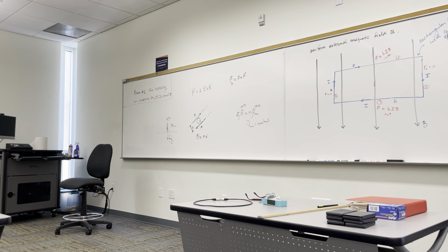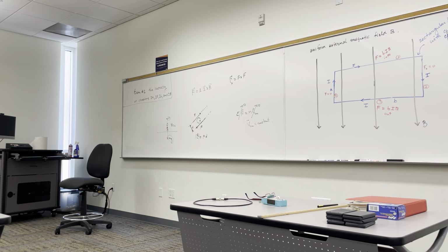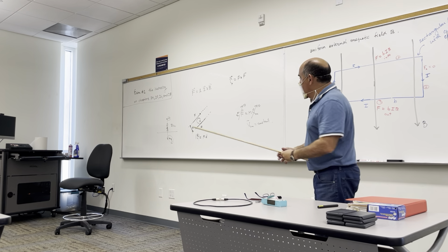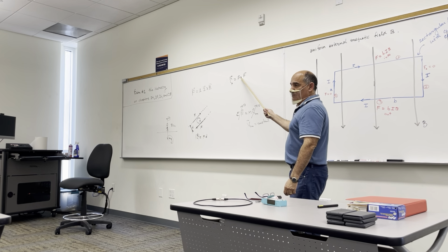So this is very easily done, if you remember that other result, of course. The magnitude of the force is I, and then if you multiply this A by this B, it will be A times B, and then the big B to the left. That'll be the torque, if you remember what the torque of a couple is. If you don't remember that, you can do the cross product.